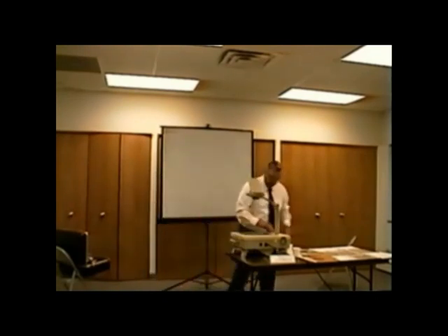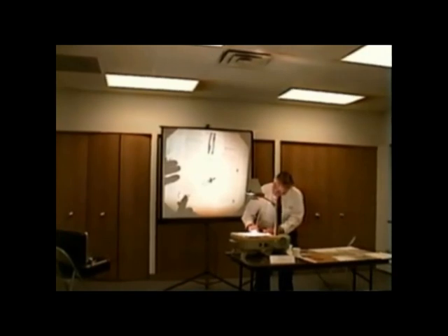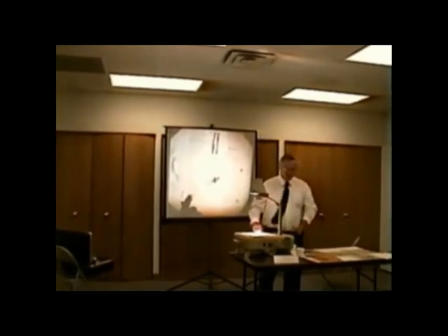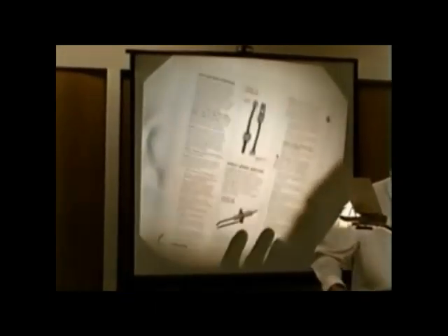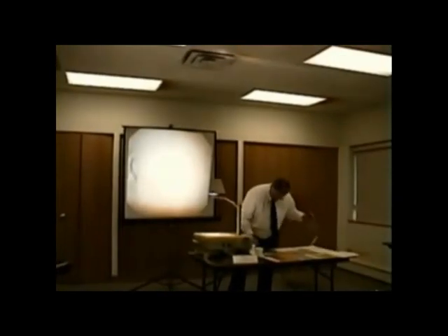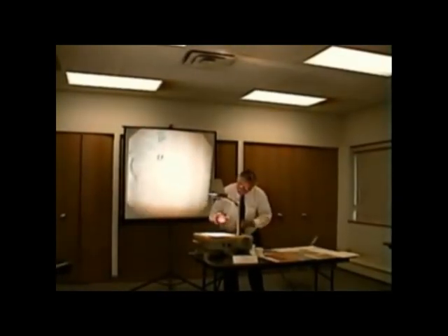Okay? All right. So if 45 to 250 is good, or not good, if we're getting close, and we already talked about what is good. Kevin, I'm going to ask you for the reading on this, so let me go get the job site sheet. What can we put down that we checked with an ohm meter then on the igniter? 175. Good. 175 ohms. Perfect. Okay? All right. We're getting there.